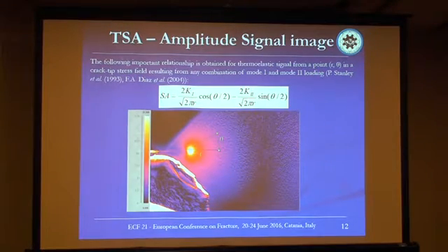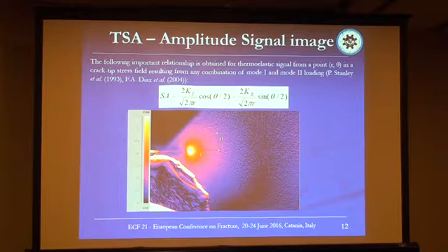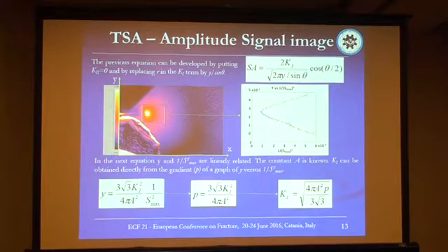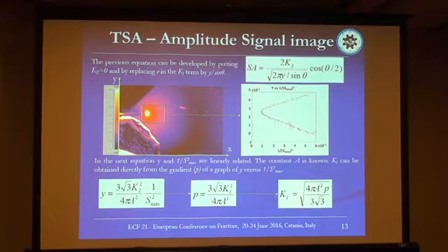With thermoelastic stress analysis, it's also possible to evaluate the stress intensity factor. So we can relate the thermoelastic signal to the stress intensity factor during the test. By simple consideration, considering an area around the crack tip position, we can evaluate the trend of the maximum signal during the test. So, it's possible to evaluate the stress intensity factor only knowing the constant calibration of the test.